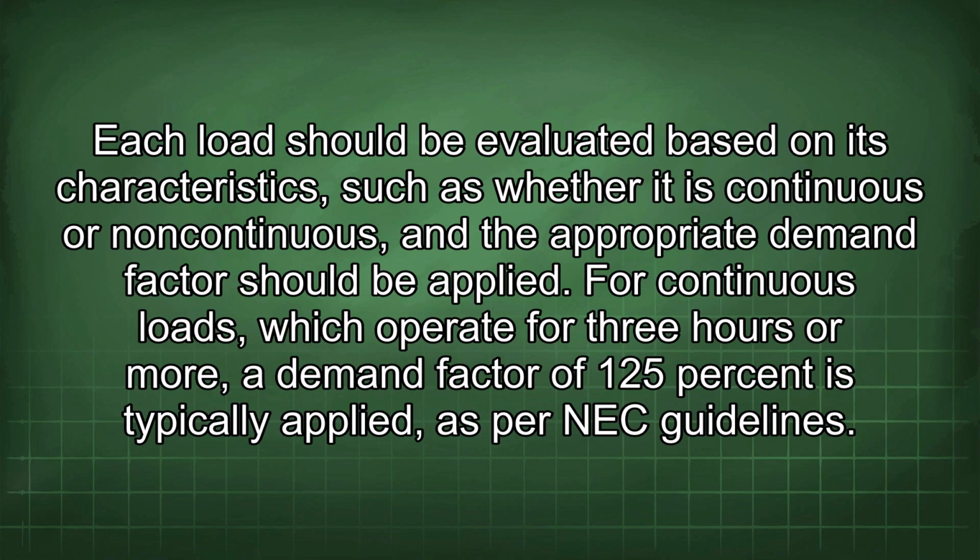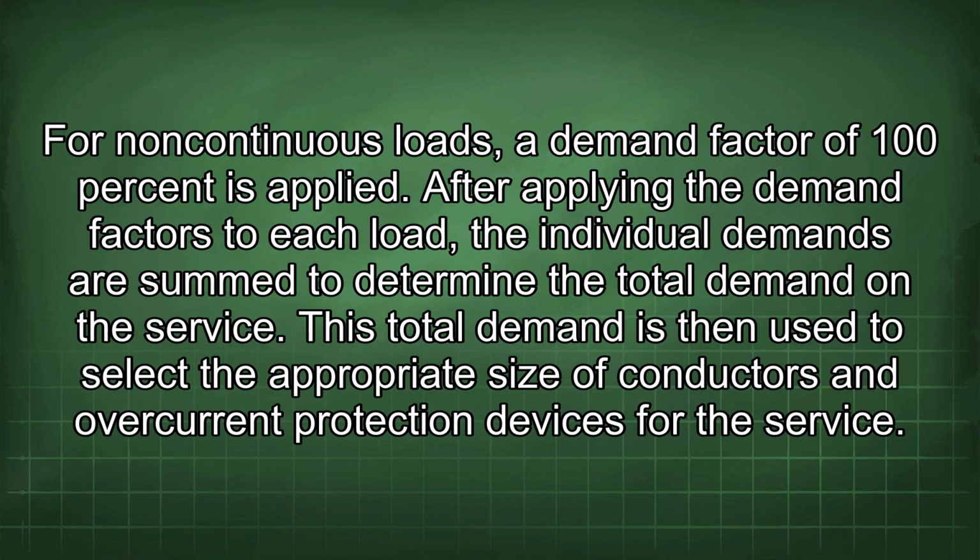Each load should be evaluated based on its characteristics, such as whether it is continuous or non-continuous, and the appropriate demand factor should be applied. For continuous loads, which operate for 3 hours or more, a demand factor of 125% is typically applied, as per NEC guidelines. For non-continuous loads, a demand factor of 100% is applied.